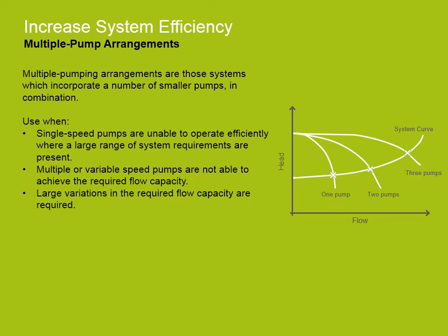Multiple pump arrangements. Because single-speed pumps are unable, in most cases, to operate efficiently where a large range of system requirements are present, and multiple or variable speed pumps are not able to achieve the required flow capacity, it may be necessary to employ multiple pumps.